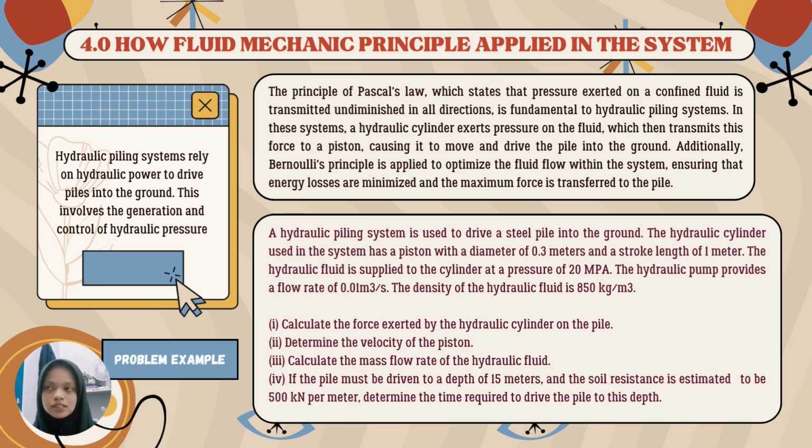Pascal's law states that the pressure exerted on a confined fluid is transmitted undiminished in all directions, and is a fundamental of the hydraulic piling system. So in this system, the hydraulic cylinder exerts pressure on the fluid, which then transmits the force to a piston, causing it to move and drive the pile into the ground.